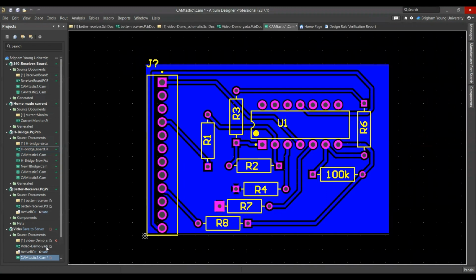thing. These CAM files can be found in the computer, specifically Windows, by going to Windows, Users, Public, selecting Public Documents, Altium, and then you'll find your video, project outputs. You'll find all your CAM files. Normally, these are turned into the shop here at BYU in a compressed file. And I'm sure for class, you'll probably compress all of them into one file to turn in as well. Okay, so